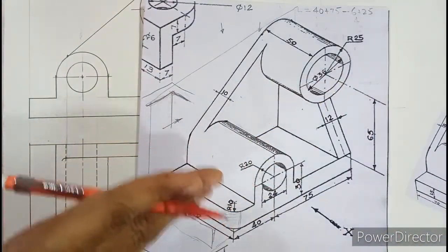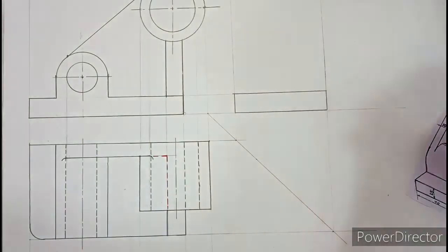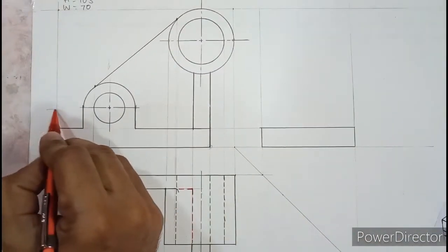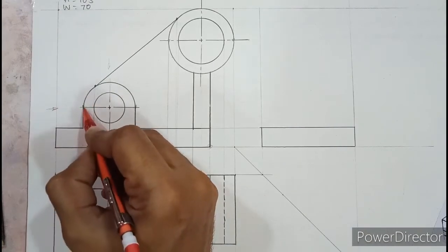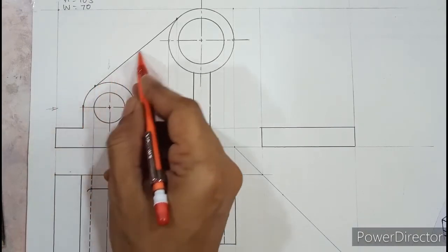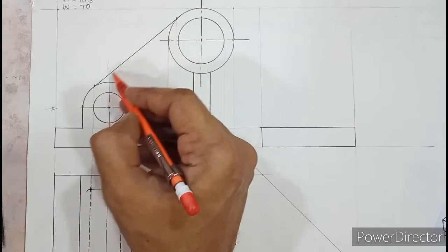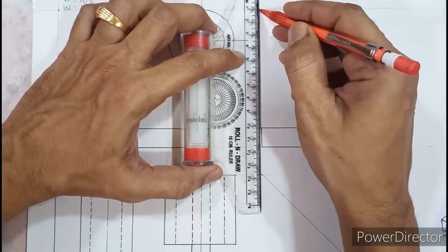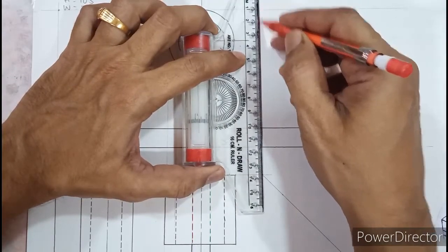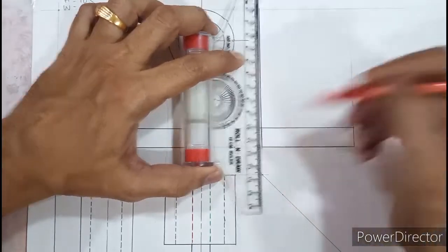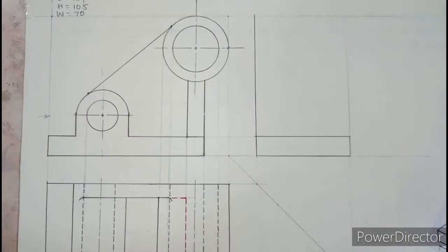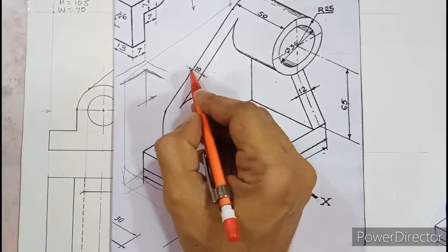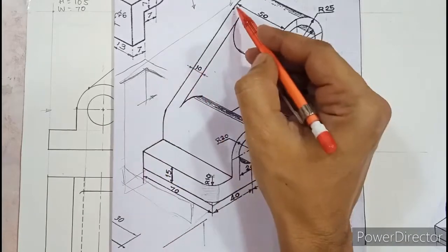Okay, and that too on the side view. If you look here, it is on the left side. So in the left side, if you look at the diagram, look from the side, this straight edge, circular edge, inclined, again circle, together if you look, it is seen as one single vertical line. So that we need to draw here. Okay, so that edge is ready. So once that edge is ready, you can see rib. So the rear edge is ready.